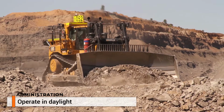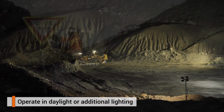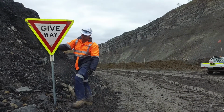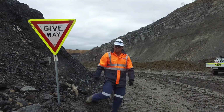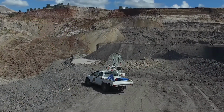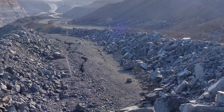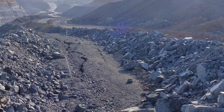Restricting operations to daylight hours only, or installing additional lighting. The number and nature of controls is governed by the consequence and likelihood of a slope failure occurring. Slope monitoring and implementation of standoff zones are two of the most commonly applied and effective controls if managed correctly.